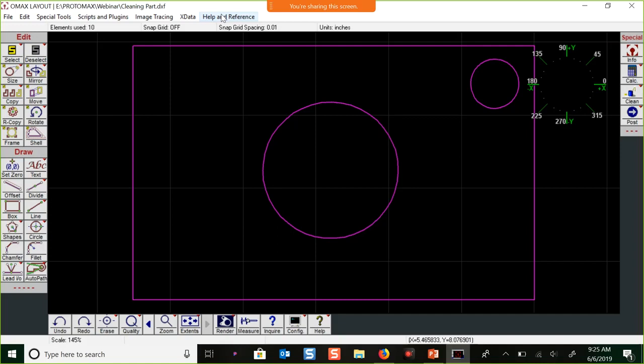Hypothetically, if you've got a 12 by 12 sheet of material that you put in your ProtoMAX to cut and your part's 11.5 by 11.5, then you're missing a 1/2 inch on both sides. So you would have to offset that by a 1/2 inch to be able to find exactly where you started from, and then you could start from that point. So always record where the path was. That would appear to be a way of doing that, but we'll think on that further.